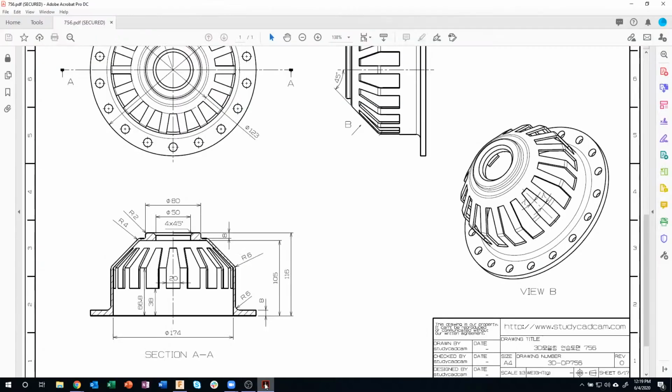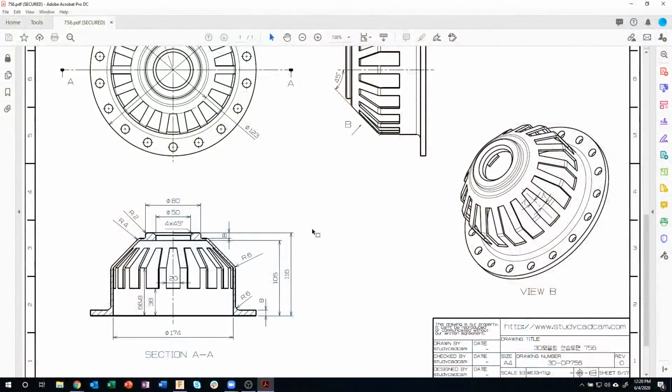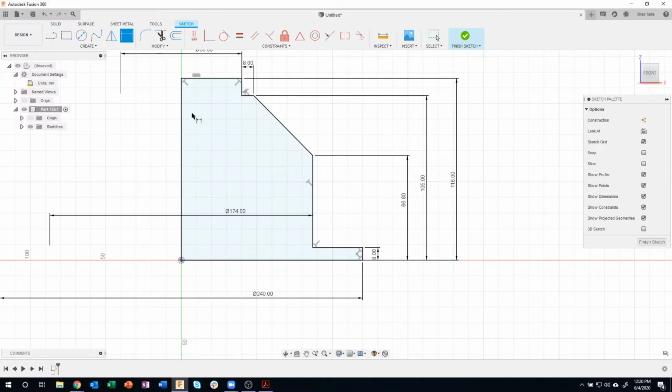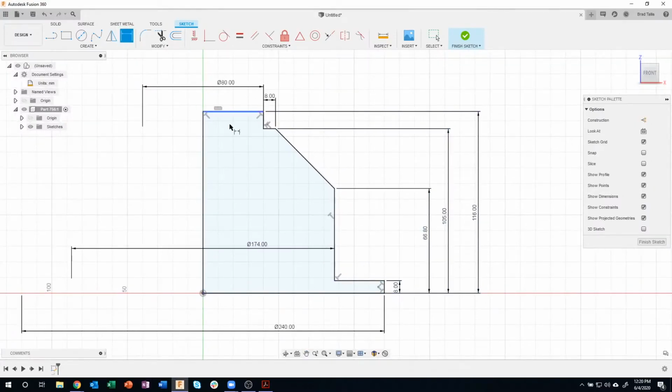Okay. So, like I said, this is literally the first time I've looked at this drawing instead of saying download and save. So I struggled a little bit trying to figure out how this thing is designed. I've now fully dimensioned this thing. So you can kind of see as we go in here, it is totally turned from blue to black, which means that my sketch is constrained. If I go in here, I can see this little lock symbol. That also means that the sketch is constrained.